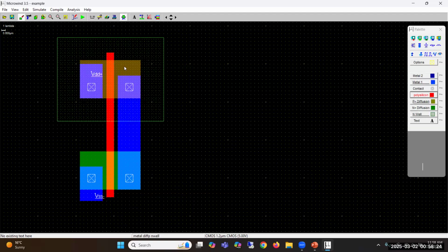If I delete, I think it will delete the layer, so I'll just show it from here. You can see this is the VDD supply. Just select it and click on the PMOS region here, anywhere. Are you able to do that? Just select the VDD supply. And yeah, so it's done.